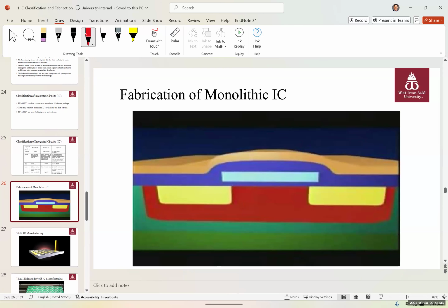This process can be repeated hundreds of times for the same chip, producing a more complex integrated circuit at each step. To create conducting paths between the components, a thin layer of metal, such as aluminum, is overlaid onto the chip, and the etching process is used to remove everything except the thin conducting pathways. Several layers of conductors separated by glass insulators can be laid down. Each chip on the wafer is then tested for performance before it's separated from other chips on the wafer by a saw. Since microchips are essentially circuits built on an incredibly small scale, they have a basic set of components.